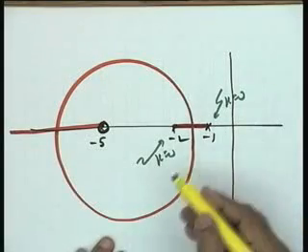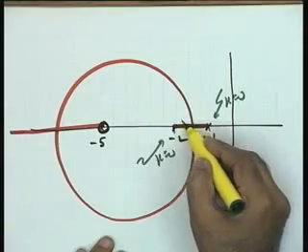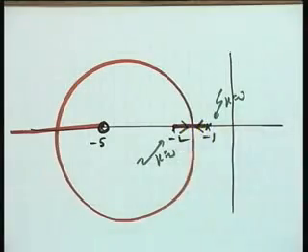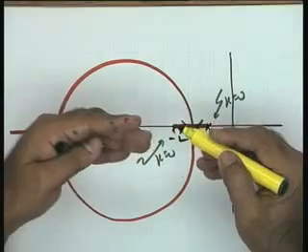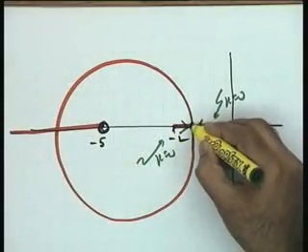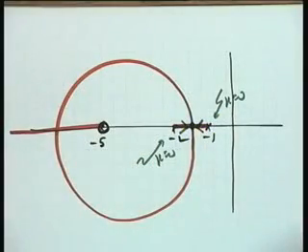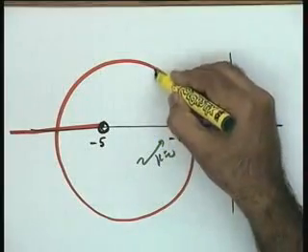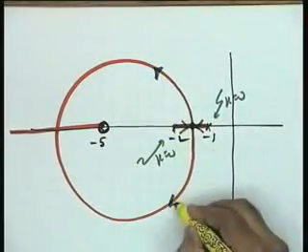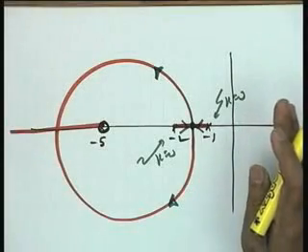What do you visualize? You start from k is equal to 0, so naturally you are going this way. You increase your value of k, you are going this way. At some value of k, your roots are repeated. Increase the value of k further, you are going this way. That is, the roots are becoming complex conjugate.